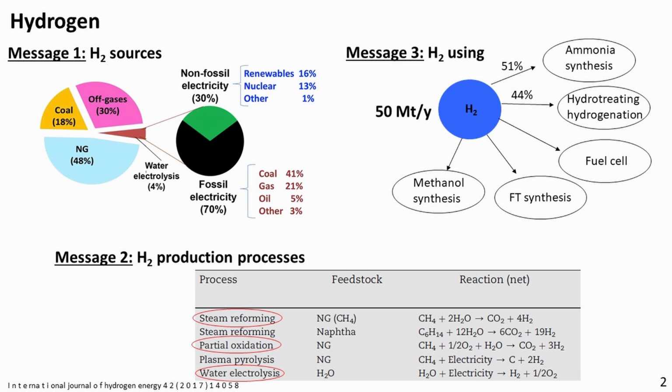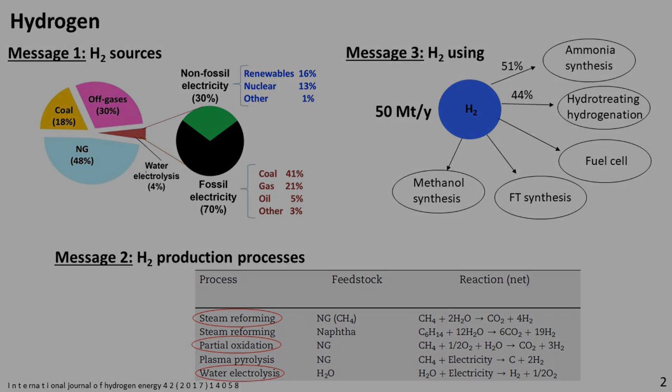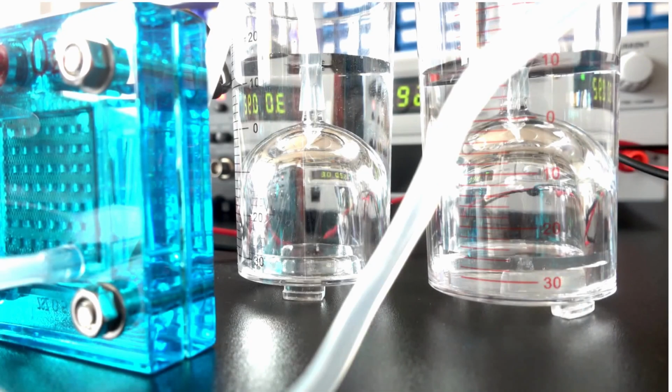Feedstock with high carbon content compared to natural gas, like naphtha, residual oil, and coal, yields significantly higher CO2 emissions, with the coal gasification process generating almost twice the amount of CO2 per unit of hydrogen product compared to steam methane reforming.